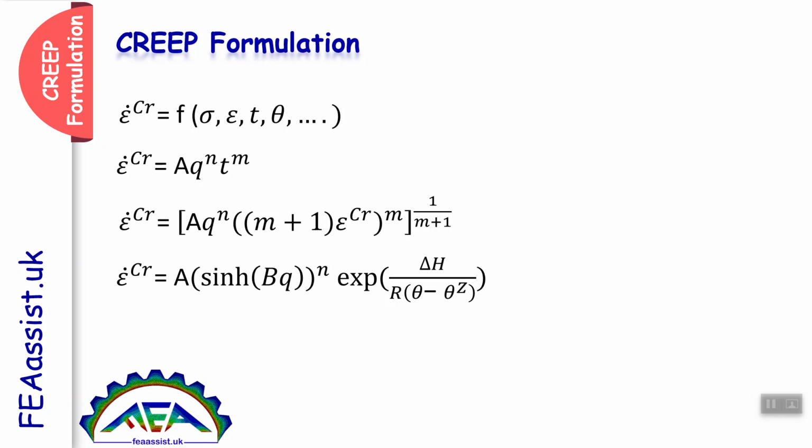activation energy and temperature. You can go to Abaqus, go to property, mechanical section, plasticity, and there you can see the creep and swelling option, and in that section you can enter all these parameters and predict the behavior. But mostly you cannot predict the experimental behaviors, and you cannot fit the experimental curves by these equations.